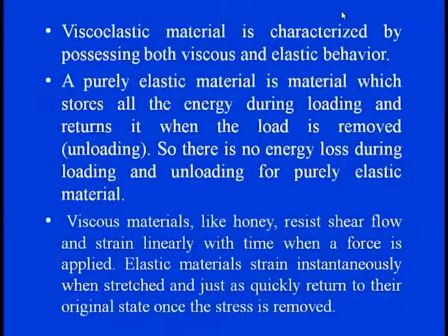Just like a spring or any elastic feature, we assume that stress is proportional to strain, or force is proportional to deformation, as in Hooke's law, which has linear propagation in releasing and absorbing energy. So there is no loss of energy during loading and unloading when we talk about purely elastic behavior. At the same time, we now add viscosity, because it is a viscous and elastic material.